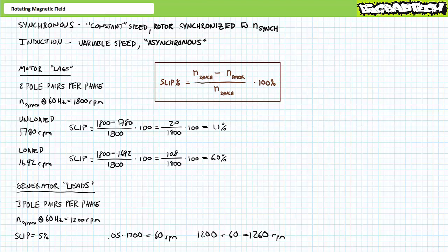Alright, that is that. I do believe we covered what I intended to and more. In conclusion, this lecture presented the rotating magnetic field common to three-phase AC machines, motors, and generators. We defined the term synchronous speed and examined those properties that influence it. Additionally, we demonstrated that swapping any two applied phase sequences results in complete reversal of the rotating magnetic field. Finally, we defined and learned to calculate slip.